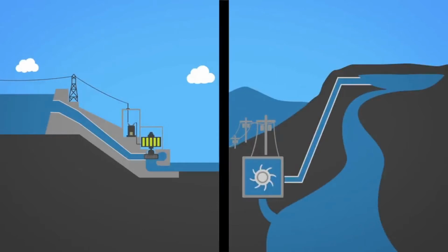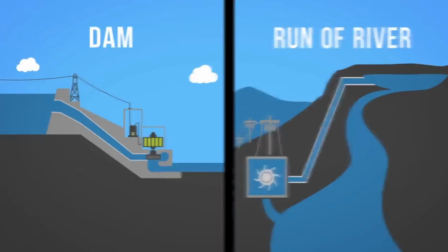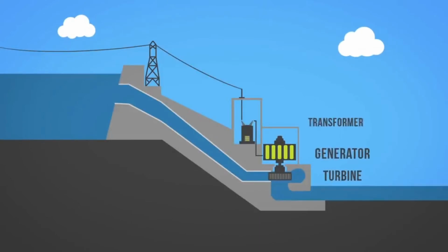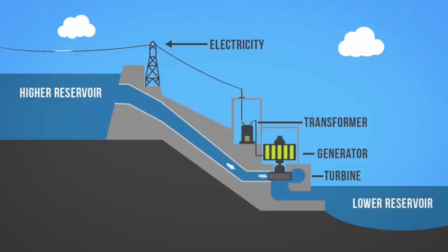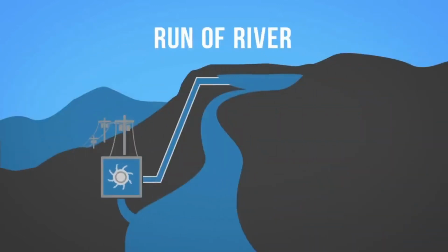The electricity travels along high voltage wire to a transformer, then onto the transmission tower where it connects to the power grid. The operation of a generator is based on a principle discovered by Faraday. He found out that when a magnet is moved past a conductor, it causes electricity to flow. In a large generator, electromagnets are made by circulating direct current through loops of wire woven around stacks of magnetic steel laminations. These are called field poles and are mounted on the perimeter of the rotor. The rotor is attached to the turbine shaft and rotates at a fixed speed. When the rotor turns, it causes the field poles of the electromagnets to move past the conductor mounted in the stator. This in turn causes electricity to flow and voltage to develop at the generator output terminals.